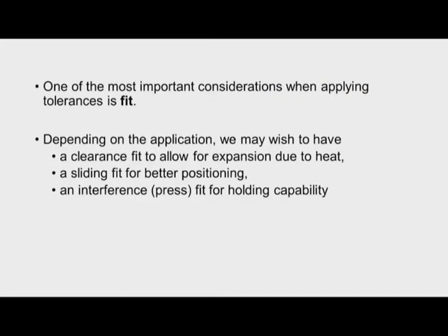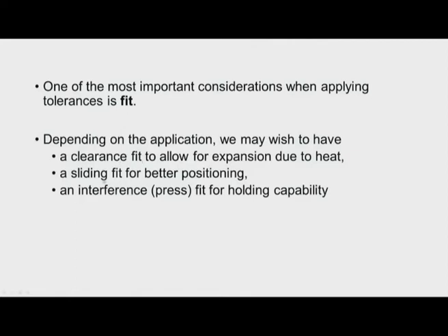Depending upon the application, sometimes a clearance fit is also used to allow expansion due to heat, due to continuous usage of the work part, for example a sliding shaft or a running shaft. There will be an increase in temperature, because of that the shaft may expand, and if sufficient space is not available it may get jammed in the hole. So to allow for expansion also some clearance is allowed. A sliding fit is used for better positioning, and sometimes an interference fit is used for holding the parts together.